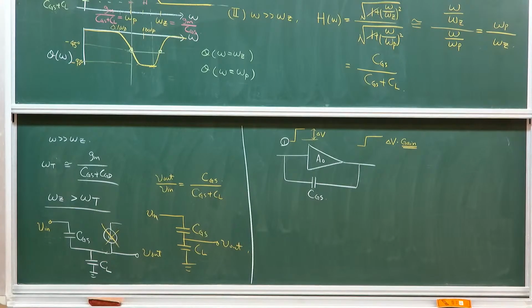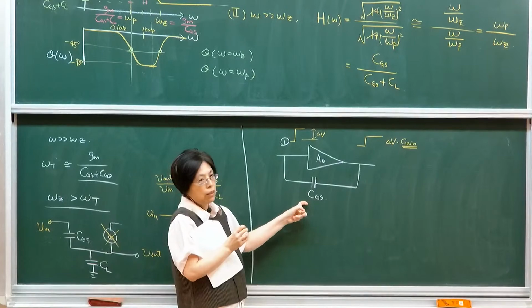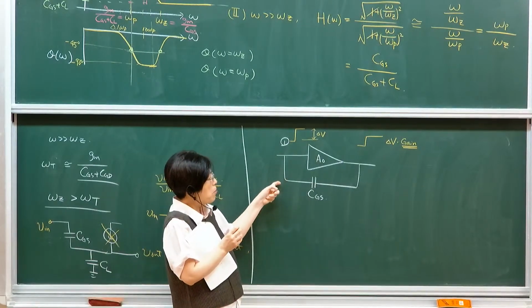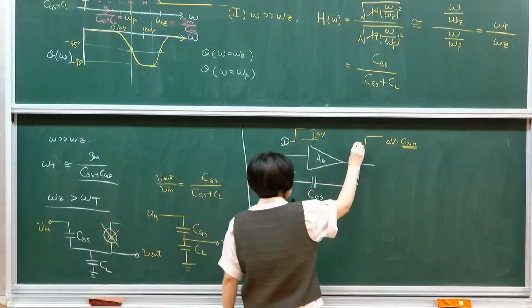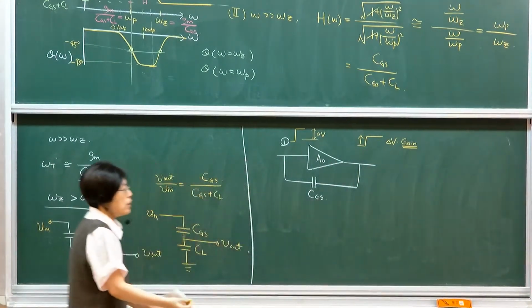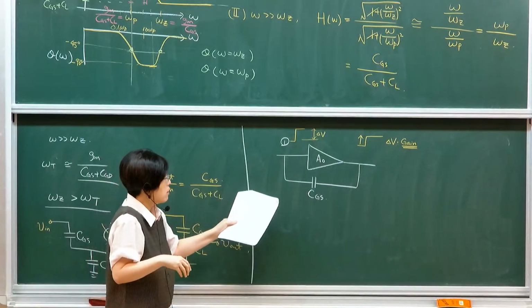In an ideal case, this capacitance can be 0. The effective capacitance from the input terminal can be 0 because it's moving in the same direction. Okay? Instead of having a sinking opposite electrode, you have a rising opposite electrode. So you have someone to help you, which reduces the charge that needs to be added on CGS.